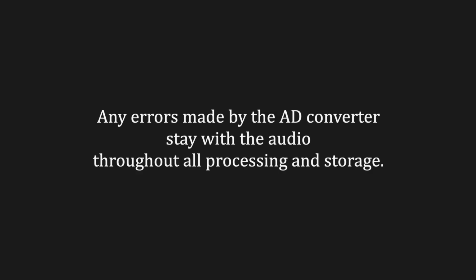The analog to digital converter. The AD converter is the core component in the encoding stage of a digital audio system. Its partner, the digital to analog (DA) converter, handles playback, but any errors made by the AD converter stay with the audio throughout all processing and storage. Therefore, the accuracy and quality of the AD converter have a major effect on the final sound.